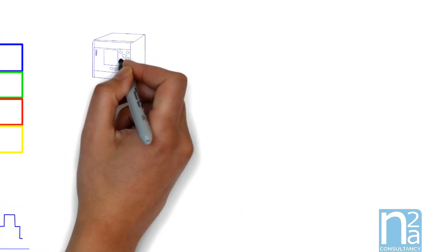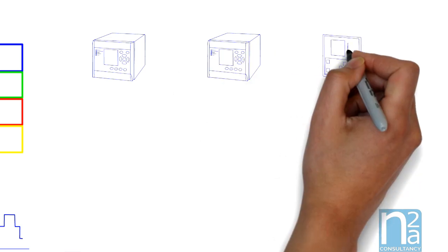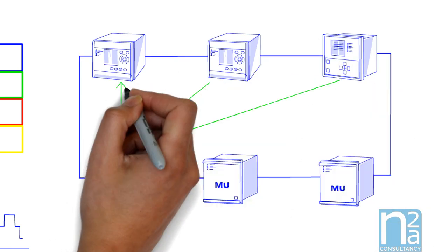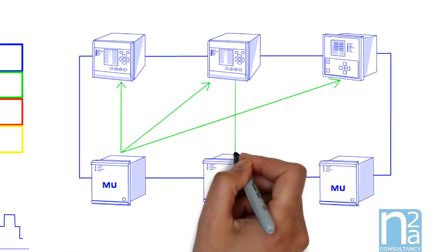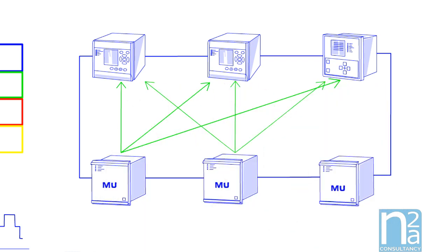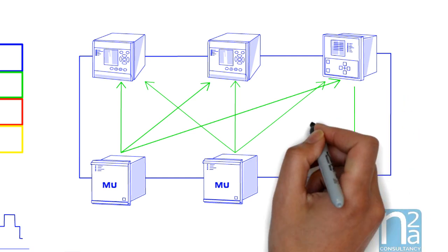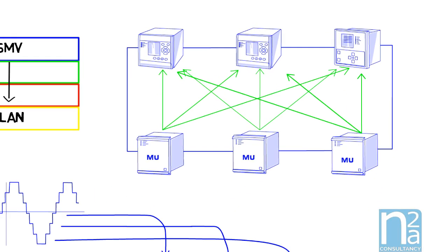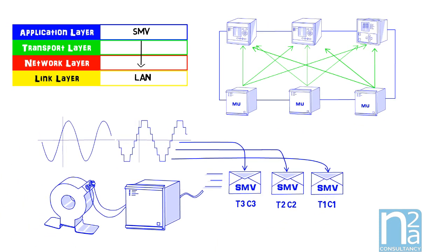This voltage and current measurement could be used by any IEDs which need the information. And this without additional wiring, just by using the process bus, which needs to have sufficient bandwidth to support this large flow of information. In medium voltage application, because of physical proximity between the relay and the switchgear, it is not much used today. But the possibility to share values of voltage and current, and the absence of copper wires in the medium voltage compartment could be an advantage.